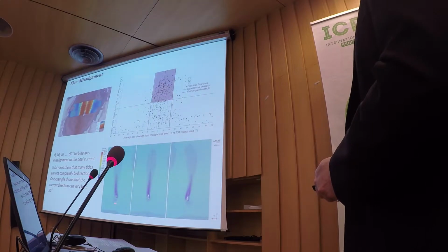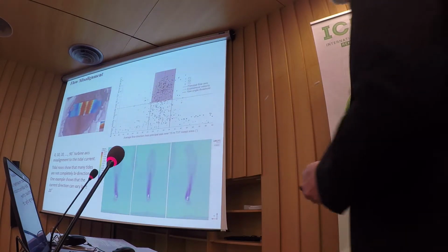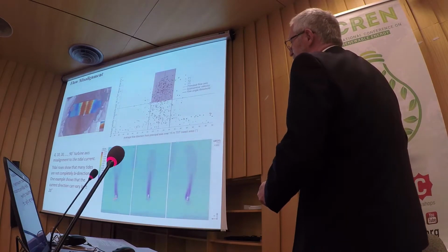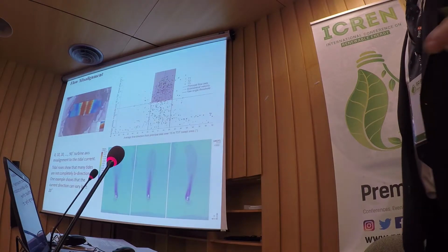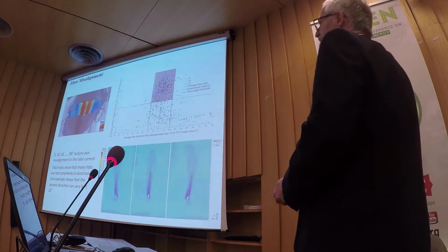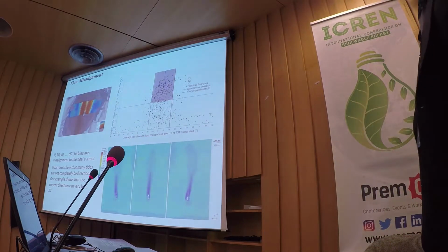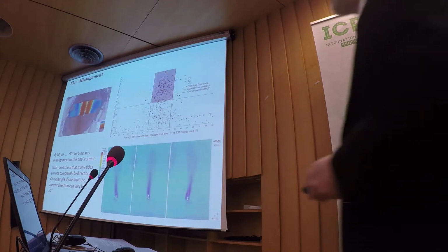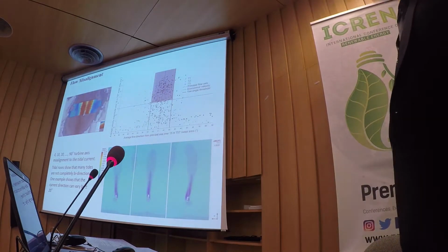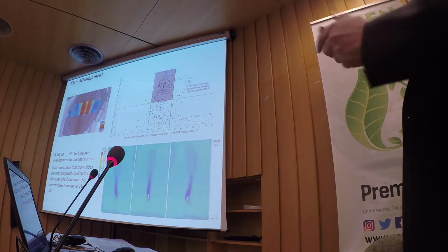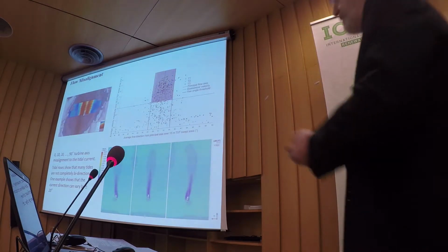What you actually get is the wake now comes off banana shaped, and you get, for obvious reasons, a decrease in the power average, a decrease in the thrust average, but a large increase in the bending moment that's translated through the blades to the end of the drive shaft. Again, those are then going to have to go through the seals, the bearings, and everything else. Any sort of wear and tear on those, failure can follow.